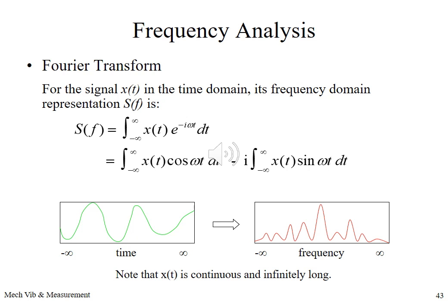So a series of points. In this case, it's a continuous function again, so it's got an infinite number of points. We can represent time domain signals in this way, and we can switch between frequency domain and time domain to our heart's content. No information is lost when we calculate the Fourier transform to get the frequency representation of a signal, so we can go back to the time domain version of the same signal.